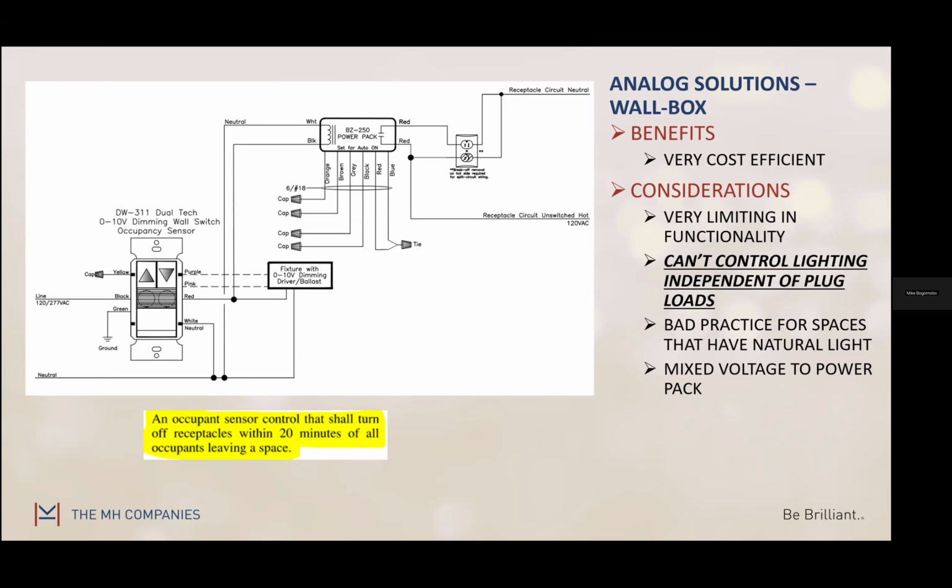So if you can, in the meantime, throw in a note if you have plug load controls in your project that basically states that your lighting loads need to be separately, manually controlled, separate from your receptacle loads, which just need to follow the occupancy sensor signal in that space. There are multiple different ways of getting that done: wired, wireless, digital, analog, a bunch of different ways. So there are options.